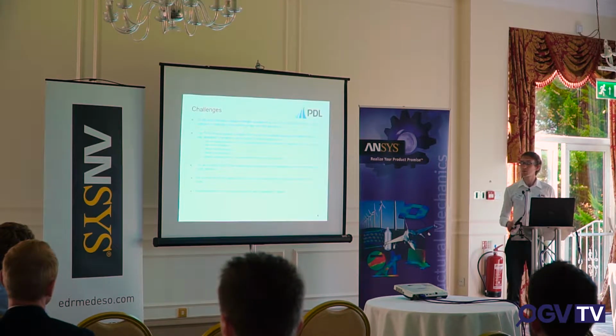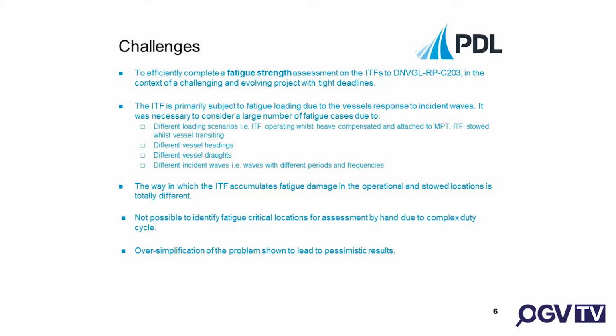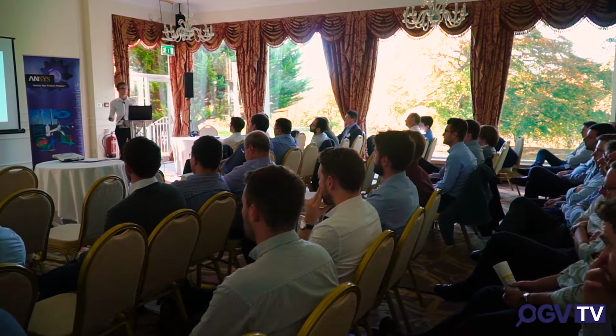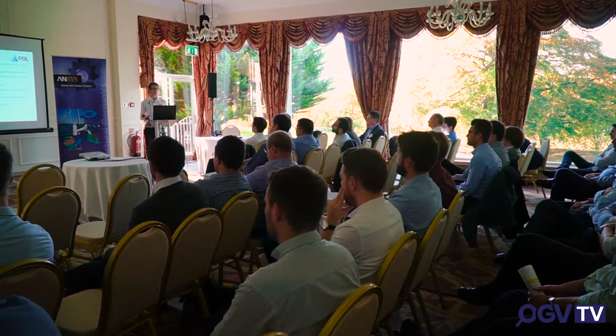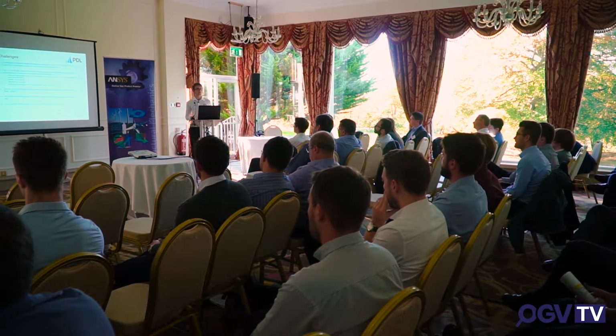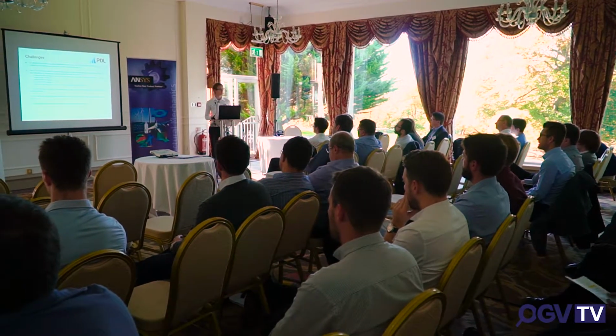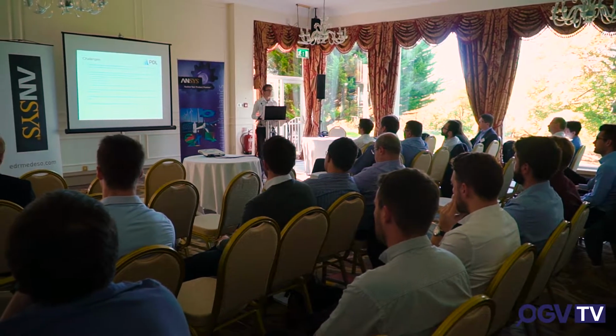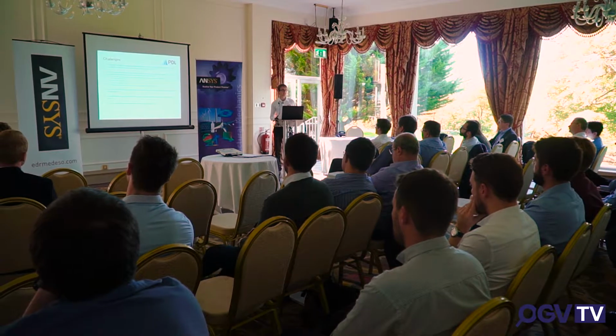So all of this means it's A, how to model all of those different loading scenarios, and then B, how to actually know where your fatigue critical locations are. Something that I've done, and maybe many of you have done as engineers, is if you've got a simple loading cycle, then you might model that. You might apply the loading in ANSYS, see what stresses and stress range you get, pick a fatigue critical location, do some Excel calculations.